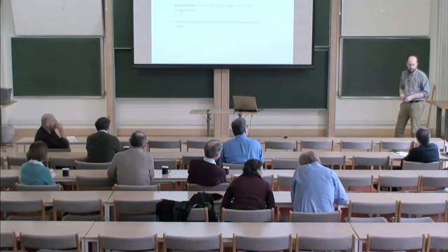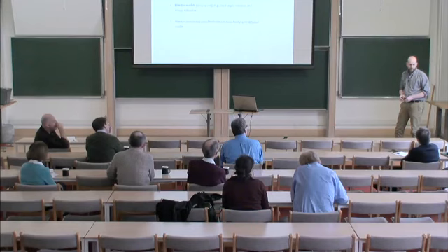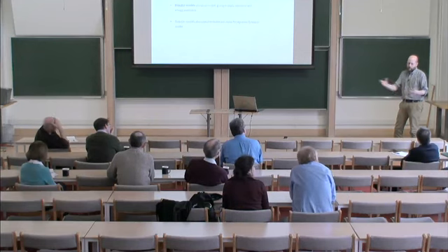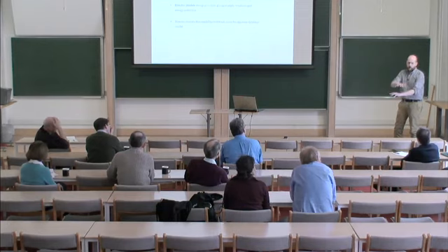You do. So you have to use in-plane fields, with interdigitated electrodes for each pixel. Because it's bistable, you can use a passive matrix scheme. You can just put it along columns and rows, and then each pixel you can pick out relatively easily.